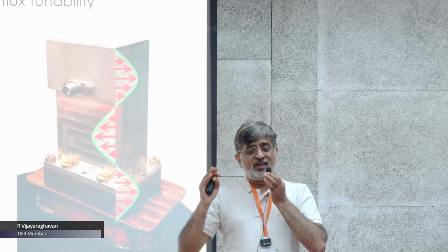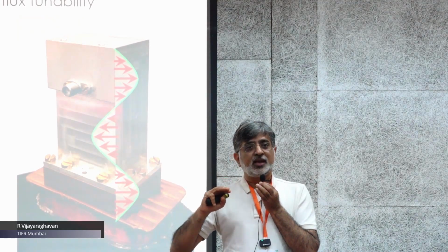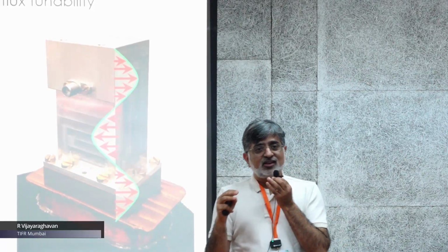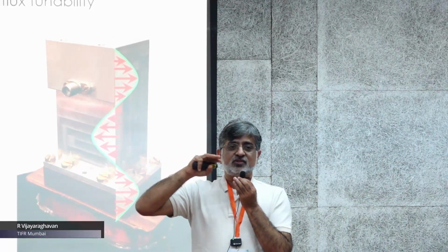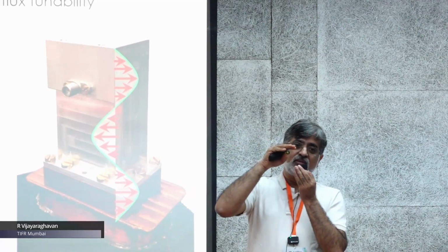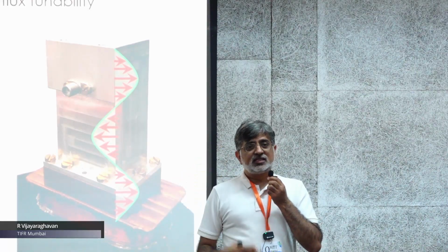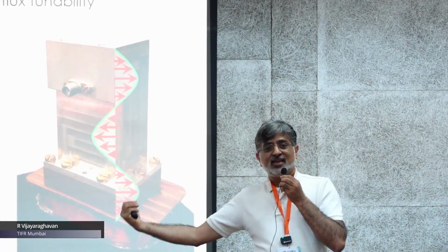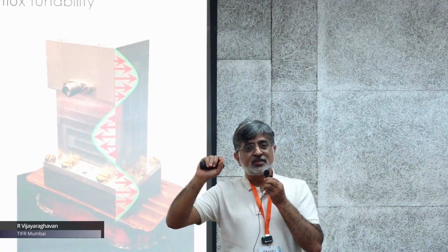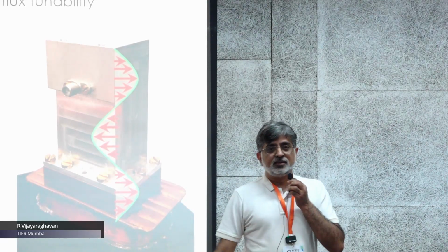Ultimately, for a well-designed qubit, the decoherence times are set by microwave frequency absorption happening in the circuit. Usually in the dielectric, it could be oxide layers on the surface of the superconductors, defects in the superconducting material, in the interfaces between the substrate and the metal itself. So over the years, people have improved. If you remember, I said that we moved to tantalum because a few years back, tantalum was shown to have much thinner oxides, which seems to have less losses at microwave frequencies.